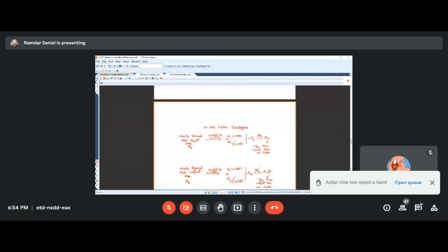Same with the output resistance. The RO was the newly formed amplifier output resistance, which when it gets scaled, depending on series or shunt, we called ROF. Then we had to take RL out before we would reach the true output resistance with feedback. So the 6 resistances, 3 input, 3 output that we introduced are all summarized here. So this is good.